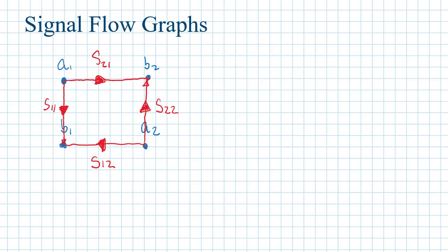representing perhaps a device under test, and we'll move the discussion along with the goal of coming up with a single expression for the input S parameter for the entire network. So we'll be able to reduce down the cascade to a single expression involving all the S parameters. And you can do that algebraically. It's very complicated. And what we'll show is you can do it sort of graphically using signal flow graphs. It still ends up being kind of complicated, but perhaps a little less so because you're using graphical techniques.